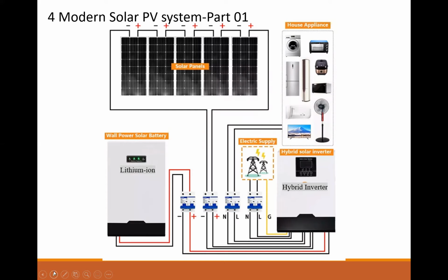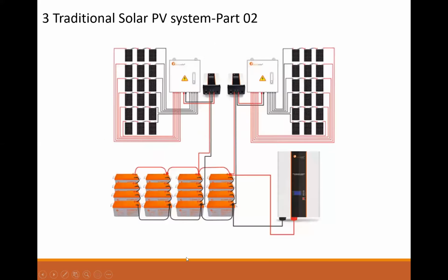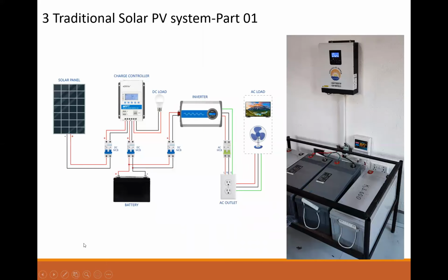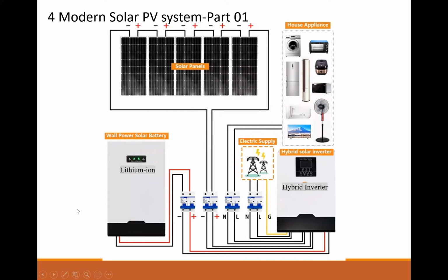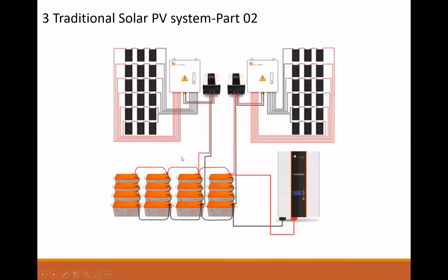One thing that can be realized is when we have got gel batteries, some of the most active loads cannot be supplied. But lithium-ion has got the battery management system inbuilt in them. So the protection when it comes to charging, overcharging, cell over voltage is enhanced. When we have got gel, we only depend on the inbuilt protection of the charge controllers.